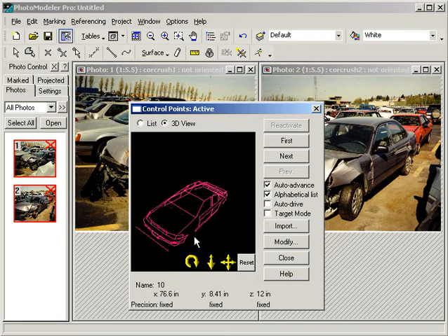Another technique for unknown photo projects, when the control data comes from another photo modeler project, is to combine the projects. For example, you would first complete a photo modeler project of the exemplar vehicle using a calibrated camera. The points in the project can then be changed to be fixed by selecting all the points in a point table and choosing the Fixed option in the Point Properties dialog. Fixed points are used the same way as control points with respect to an inverse camera project.